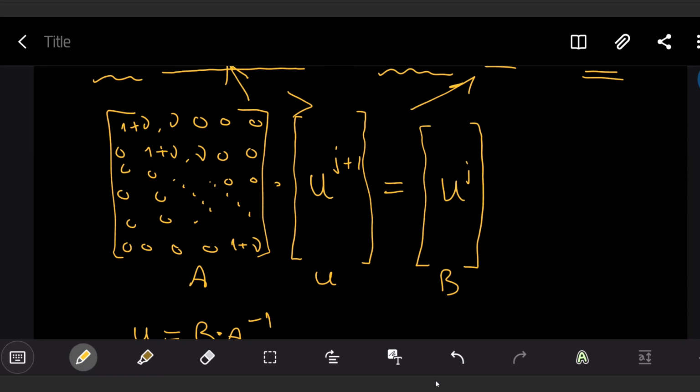So these are the two parameters: we choose between time of solution and stability of the flow. If the flow is stable enough and you are satisfied with the results, you keep this Courant number. But for every different task, this value is different. It cannot be known before you do the simulation.